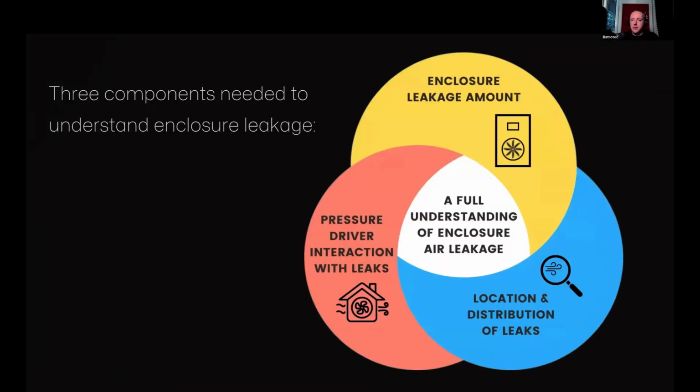So one thing that I do want you to take away from this presentation is that the blower door number that you get is not the full story. It is one part of it. And I created this diagram to really show you what you need in order to get a full understanding of the envelope leakage. And this really falls more into that existing building side, right? When you're trying to figure out why that building is misbehaving and having issues.